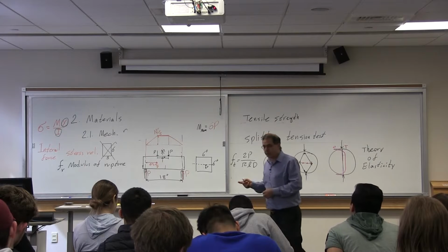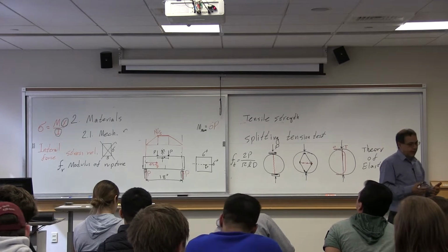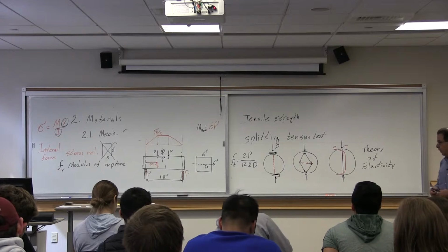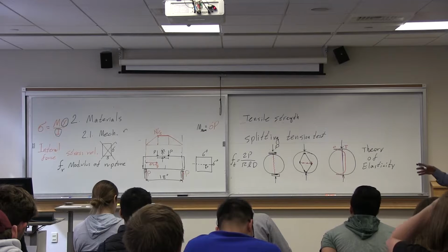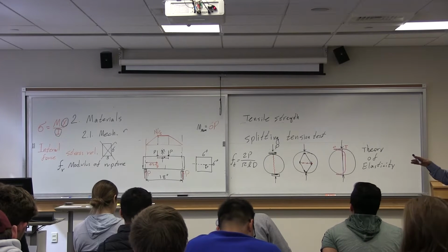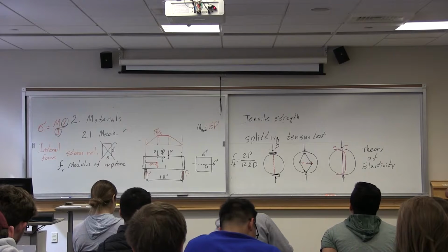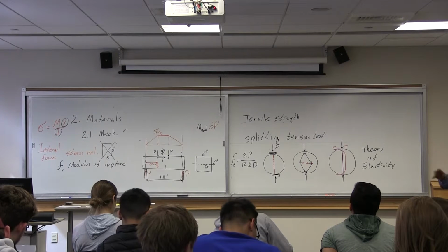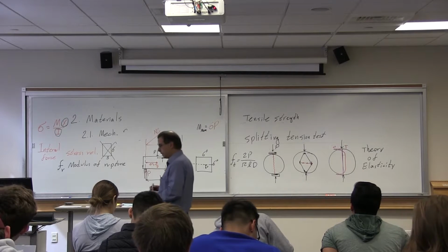Usually, modulus of rupture is a better measure of tensile strength that we use in evaluations. Roughly, modulus of rupture is 10% larger than tensile strength. It's not a perfect relationship, approximately 10% larger.